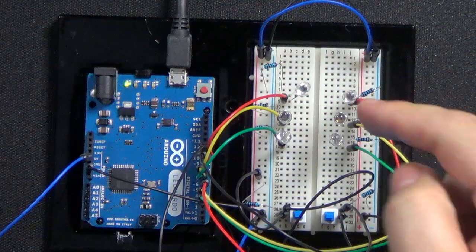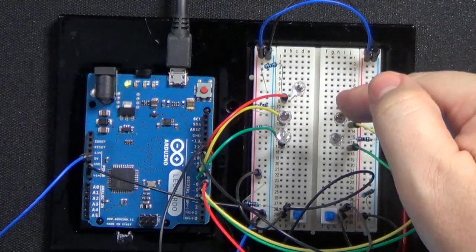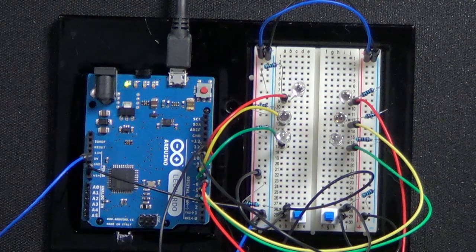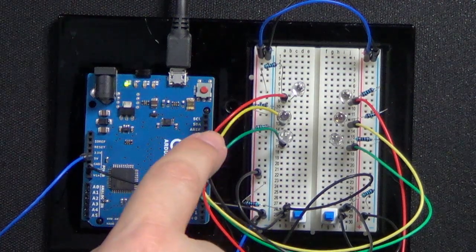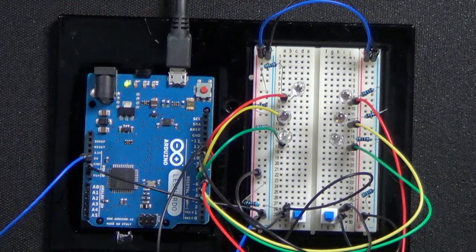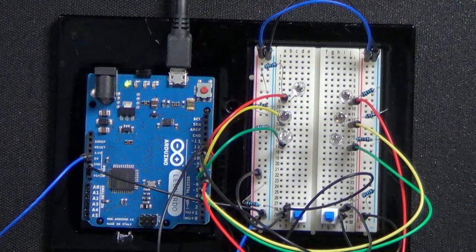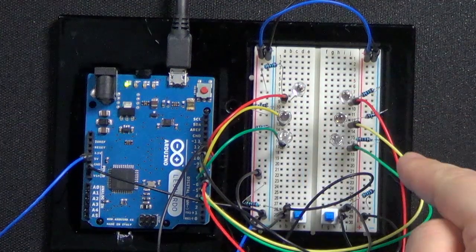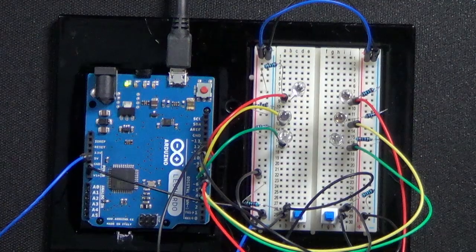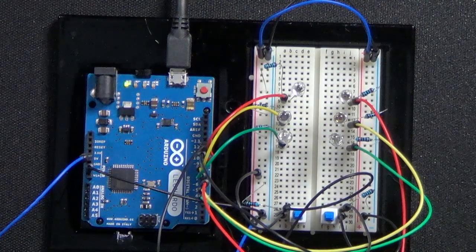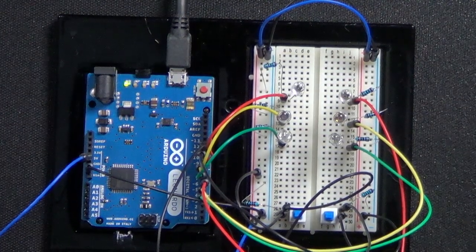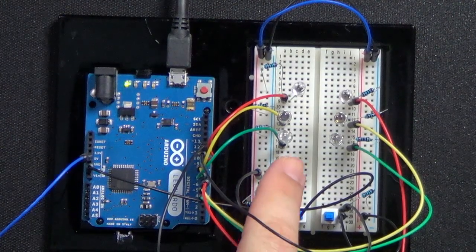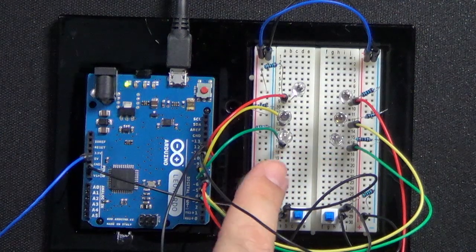You can barely see them, but I have 6 LED lights here, and the reason you can barely see them is they're actually clear, but when they turn on, they're different colors. And you see a red wire, a yellow wire, and green wire. Those are our positive to the LED lights. And then on this side, I'm going to call traffic light 0 and traffic light 1. And the reason I'm calling it 0 and 1 is because in my code, that's how I did it. And you remember when you're writing stuff in the Arduino, everything starts at 0, not at 1. So on the left side is 0, the right side is 1.